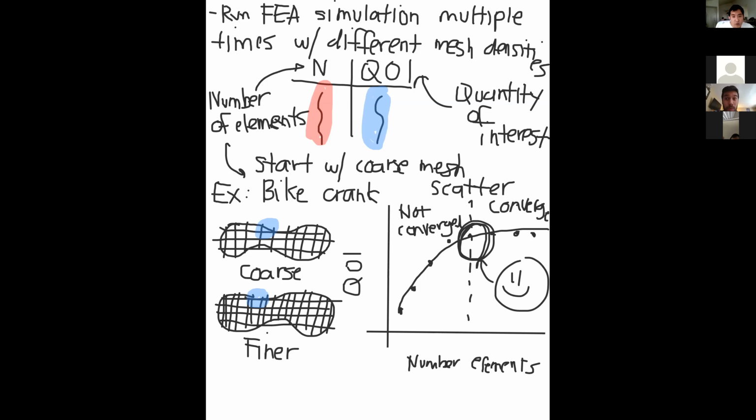At that location, we maximize the accuracy and minimize the cost. That point is the best mesh density to run our simulation. We can refine the mesh some more, but we get diminishing returns, where it doesn't get much more accurate but we're working that much harder. So that's the sweet spot, the maximum accuracy for the minimum cost, and that's what the mesh convergence test shows.